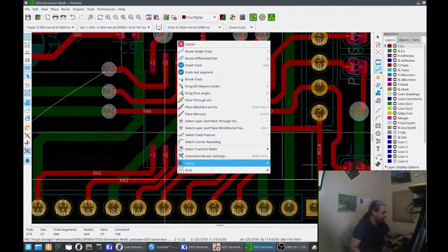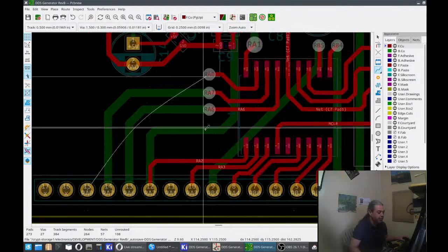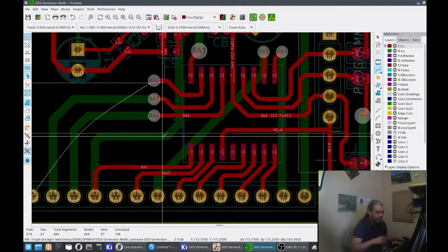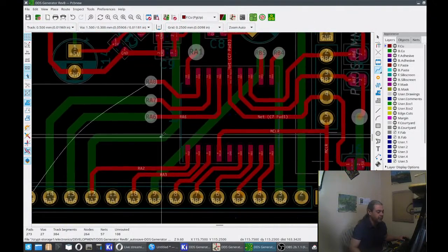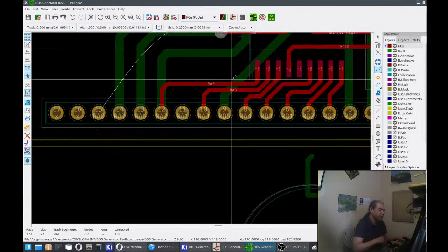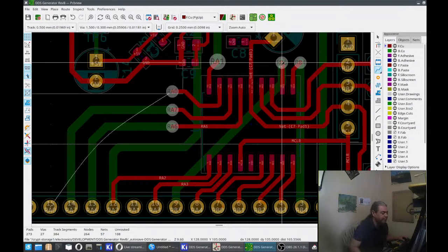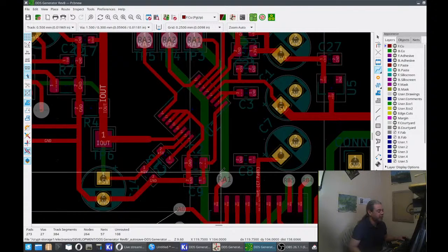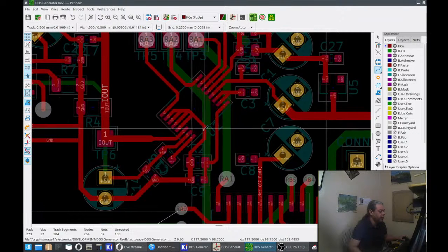So now I'm looking at it, I don't need to use vias there. I won't. I don't need to use a via there. RB, pin 2 and 3 on that header. Those need to be done. RB4, RB5. This one here, that justifies a via. This one, not yet, but it does. So it does count. RA2, looks like it. RA3 also needs to go.